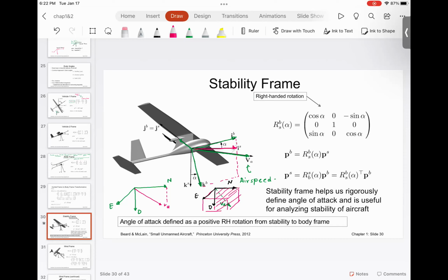If the airspeed is very low, then the airfoil will not generate any lift and the aircraft will stall. So for an aircraft to fly, it needs to have a certain airspeed. Otherwise, the aircraft will stall and fall down like a rock. Airspeed is generated by the relative speed: because the aircraft is going forward, air is coming backward. So you have a relative speed between the surrounding air and the aircraft that is generating the airspeed.